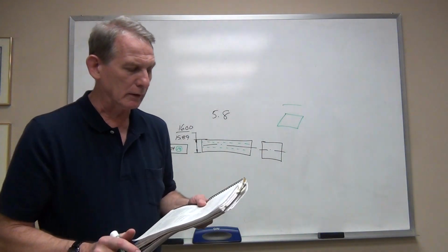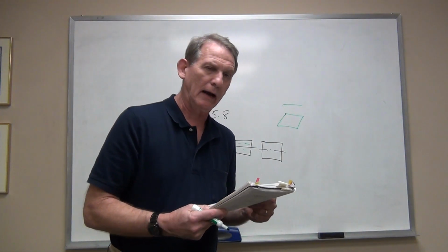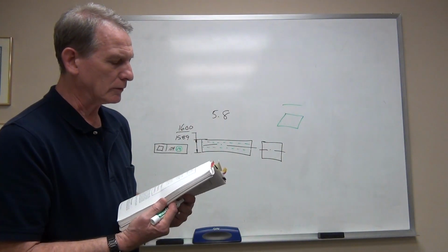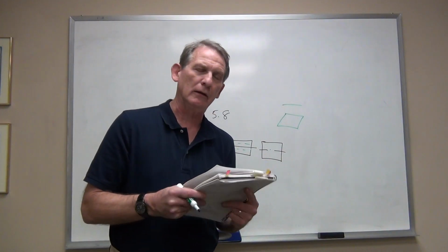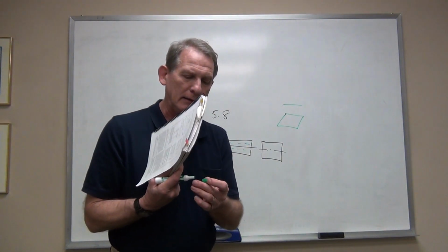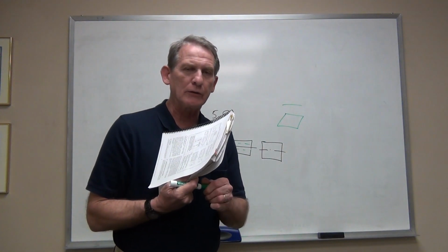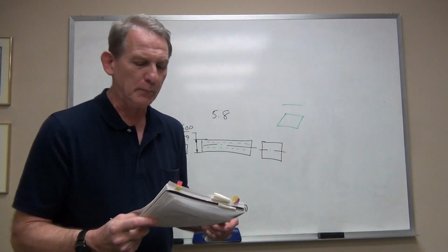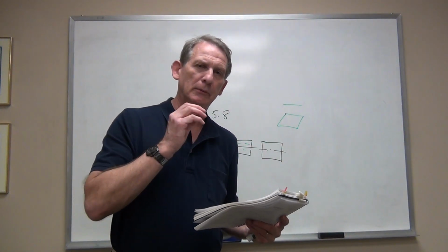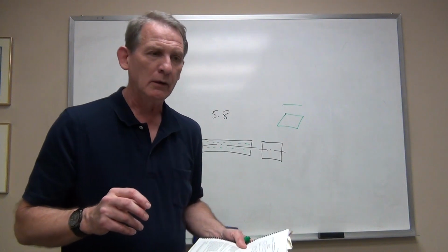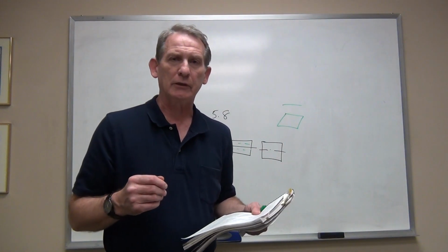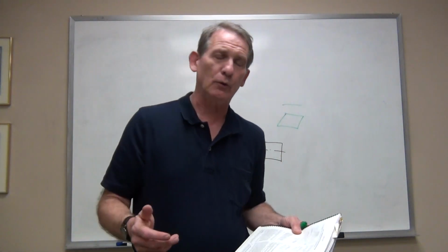I will point out in figure 5.9 where this is shown that there's a thing called an acceptance boundary. I'm not going to take the time to explain that. That is more of a tool design consideration, but it does sort of explain how you can use geometric dimensioning and tolerancing to design and actually use functional gauging, which is ultimately the goal of GD&T.